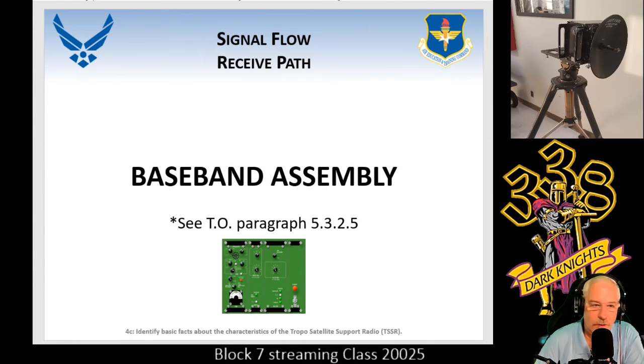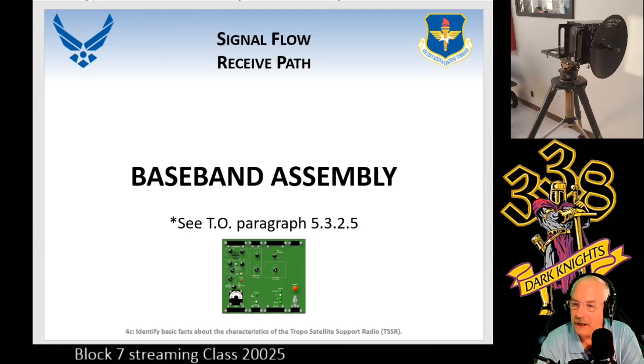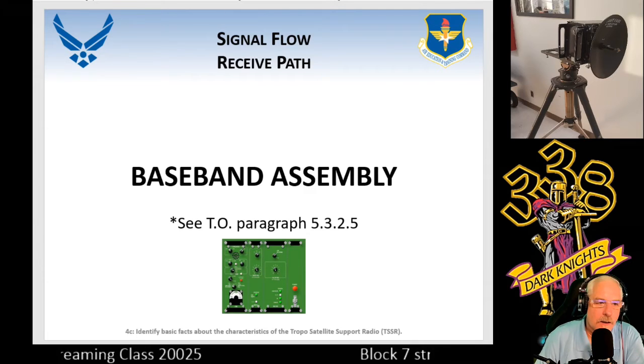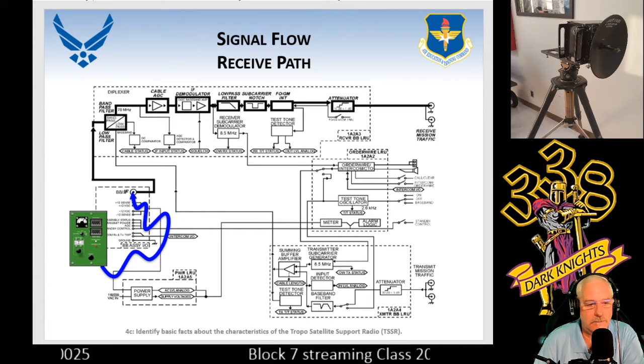It's pretty straightforward. Just follow the bold lines. And remember, this is on page 4 and 5. You'll notice at the bottom of those pages it says transmit baseband, and it'll say transmit RF. So that's for the baseband module or assembly and the RF assembly. In this case, pages 7 and 8 are the receive side of the house, and that's what we're in now. So that would be page 7, and this should be page 8. We look at the receive signal path, page 8 there.